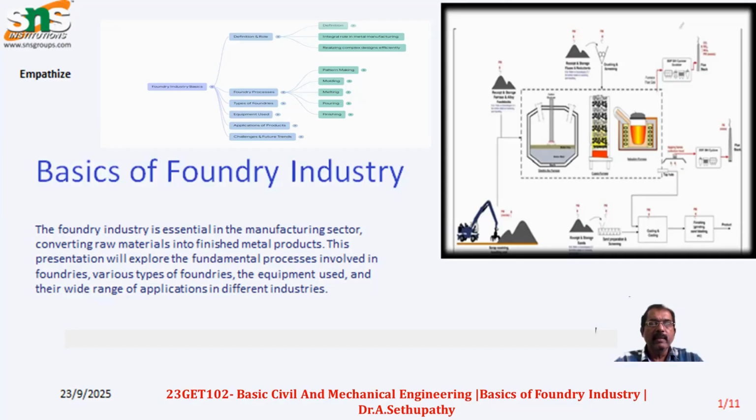After that temperature, the solid metal melts into liquid metal, the slag is removed, and it is poured into ladles. A ladle is used to tap the material from the furnace and pour it into the molds. It is for metal carrying purposes only. The metal is poured into the mold cavity, and after some time for solidification, we remove the mold sand and get a part.